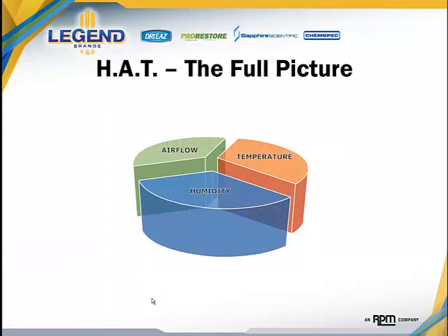As we discussed in an earlier webinar, understanding how to balance the drying system requires control and an understanding of three different components of how we manipulate the air to support evaporation. These include airflow, temperature, and humidity. In our previous discussions, we understood that the velocity of air movement along the wet evaporating surface was important, but so was the temperature of the water we were trying to evaporate. And finally, the amount of water already in the air above or around the wet surface also had an influence on the rate of evaporation.